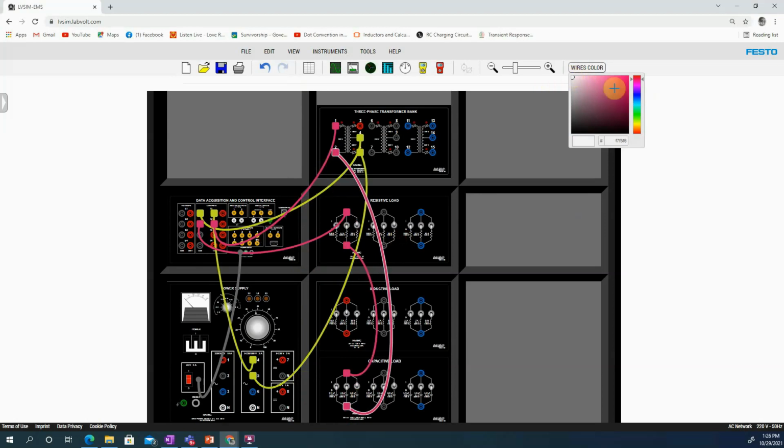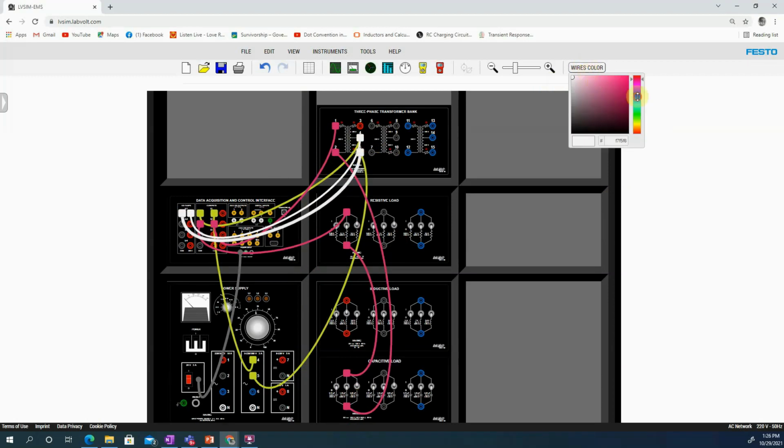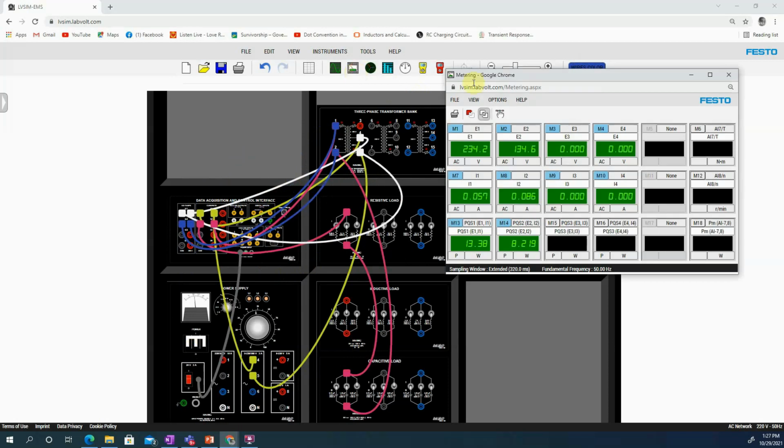We will measure the voltage to measure the primary. This is now the primary side, right? This is the primary side now. I will have to put it here, positive, E1, and I need to connect the E2. Let us connect E2. Let's adjust this. Yeah, E2 into this voltage here, right? Okay, and we can simulate. You can open this one and simulate.